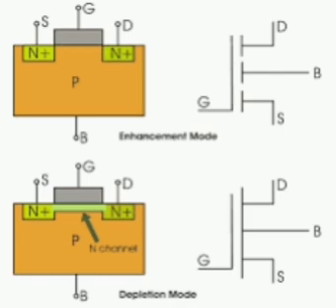and electrons respectively. Diode resistance, the dynamic or incremental resistance of diode, r equal to eta Vt by IF, that equal to dV by dI, where eta means recombination factor, equal to 1 for germanium and 2 for silicon, IF means forward current, Vt means thermal voltage. Static resistance R equal to V by I. Static resistance is always greater than AC resistance, the dynamic resistance.